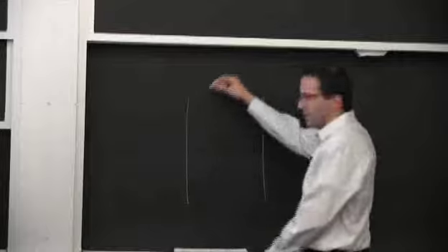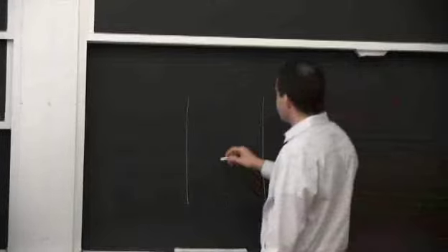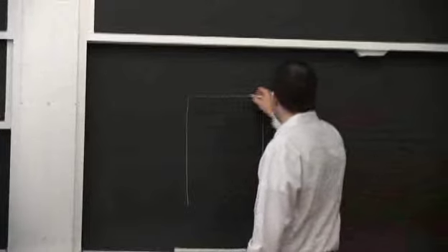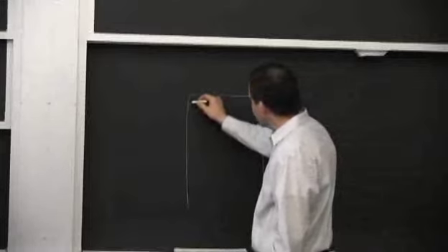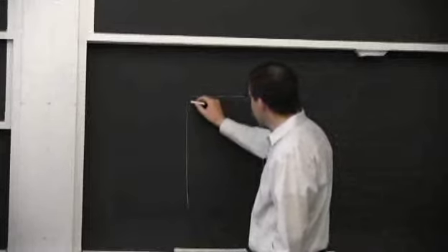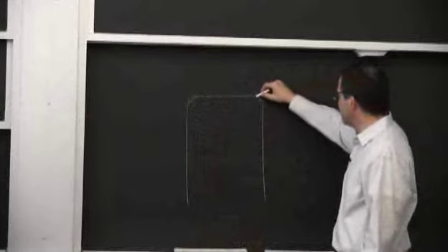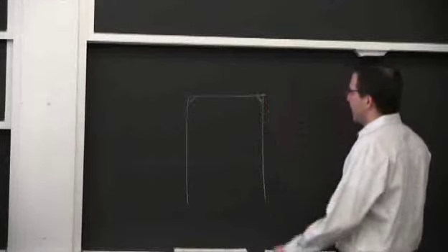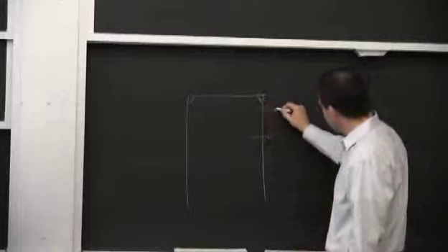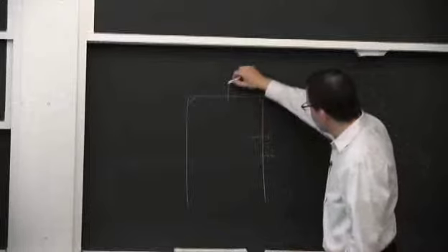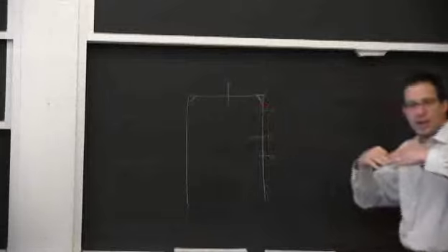it's cylindrical, and then you need a cap at each end to make it a unit. One way would be to say, I'm putting a cap right here. And then you have to worry about, well, how am I going to weld this? Maybe I weld it, best case scenario, from the inside. It's not necessarily easy to do, but it's doable. Now, when I apply the pressure, this goes this way as a cylinder. This one wants to go up, this plate, the end plate, so you're stretching out those welds.